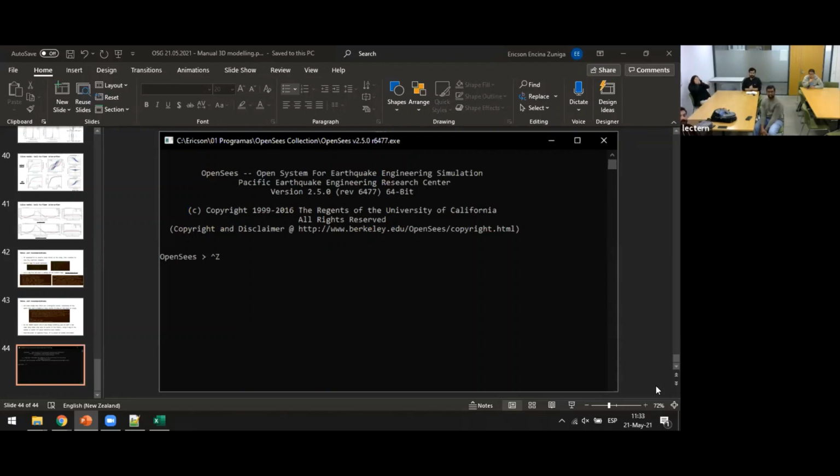How do you assess the mesh size? It's just a sensitivity analysis. You put in a mesh size, run, say, a pushover curve, then reduce the size and do it again. Overlap the curves, and keep doing that until your response doesn't change much, because it will always change. But you have to find the balance between accuracy and computational economy.